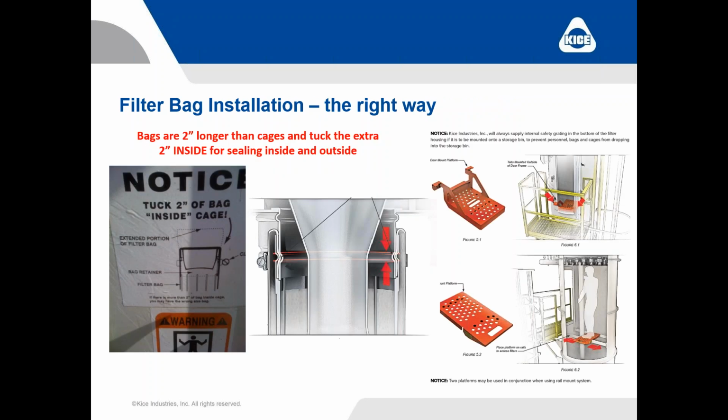Filter bag installation, again, we've got details all over our equipment. We have pictures in the manuals. A lot of times people don't adhere to these, or people are in a hurry and these don't get installed correctly. We like to suggest that when you install a filter sock, the top of that filter sock is actually going to fold over to the inside of the filter cage before you slide it up onto the tube collar. That's going to help get you a lot better seal. It's also going to help that filter cage stay up on that collar a little bit better as well.